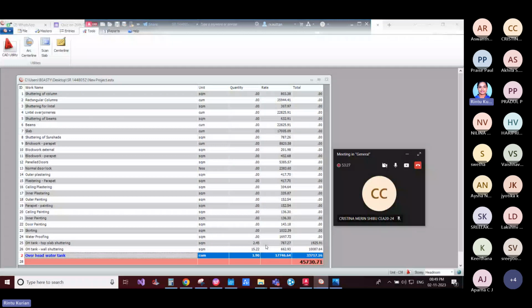This is because when you're entering the number of residents, the calculation has been done such that automatic quantity will be obtained. But for the soak pit side, you will have to fill in some manual values so that you'll get the brick and beam quantity separately. This is because soak pit is made from brick masonry. But when size of soak pit is too large, the slab cannot stand on its own. So it has to be supported by a beam underneath. And in that design, to get both these material quantities, we will have to enter the values manually. That is how the equation has been added.